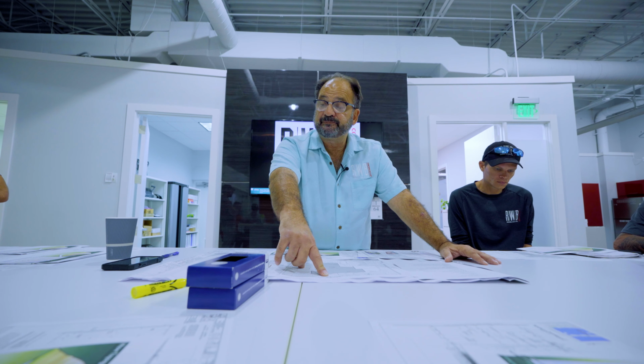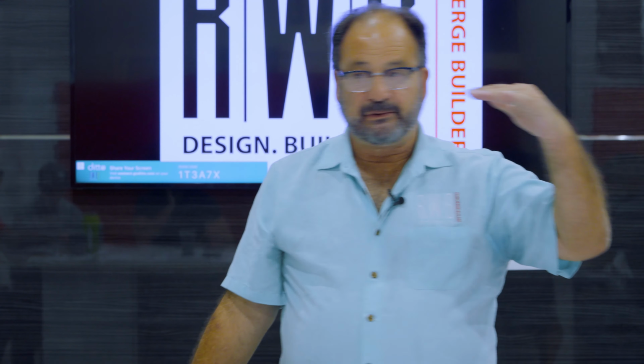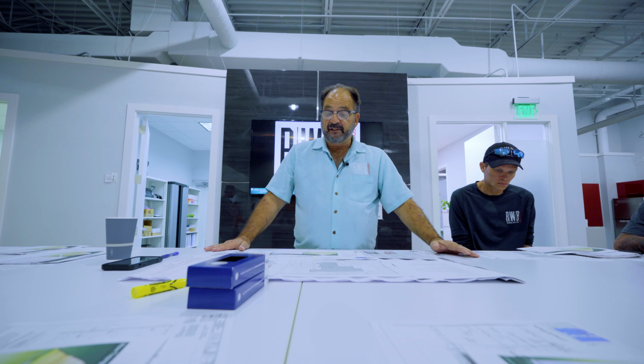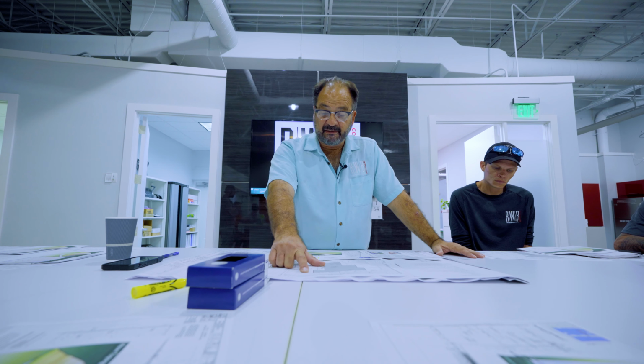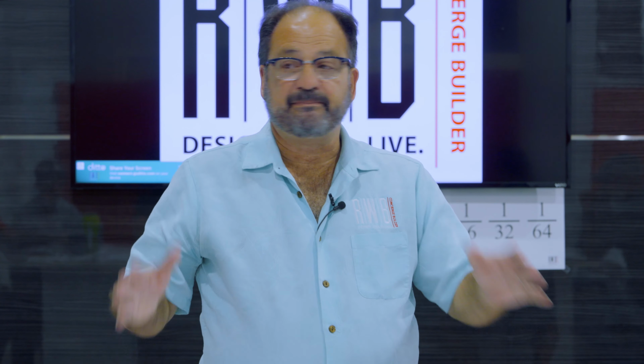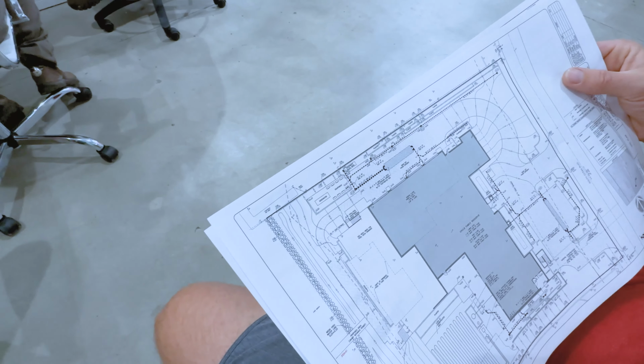Everybody see that? Now the grades, if you see the line that extends all the way to the wall, what that means is that that elevation is level all the way to the wall. The next elevation is level, and it goes down gradual. If you see the line that says 15, about halfway down the driveway, you'll see it goes to the corner of the wall and it splits. Does everybody see that? So what that means is between those two areas that split, it's level. It pitches one way, the other way, but at that point, it's level.